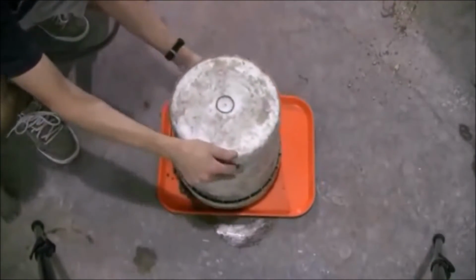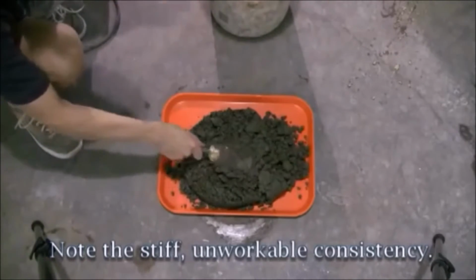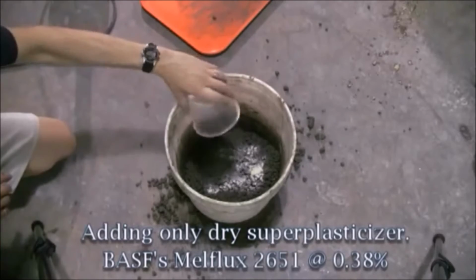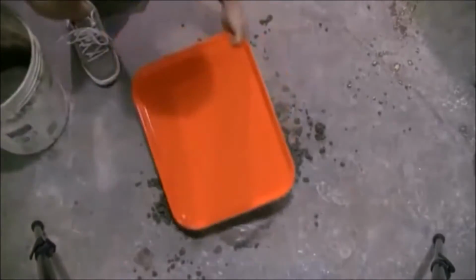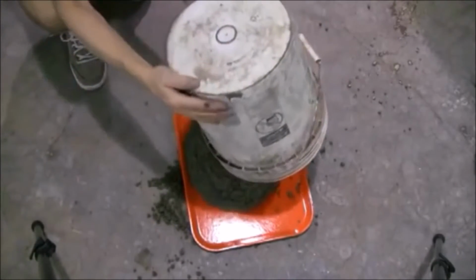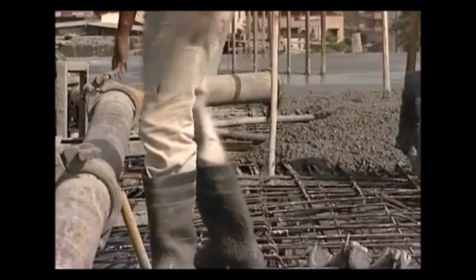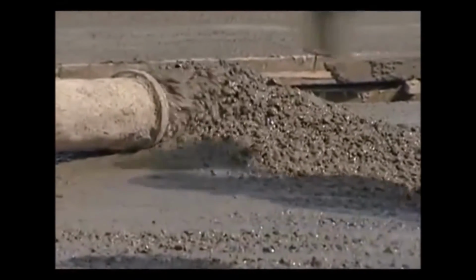As you can see, a batch of concrete with a water-cement ratio of 0.35 is inconsistent and hard to work with. With the addition of a dry superplasticizer, the concrete becomes increasingly more workable and fluid-like. Superplasticizers are classed as high-range water reducers and aren't necessarily sustainable by themselves, but in combination with SCMs and recycled materials can be used for non-structural sustainable purposes. Using this admixture, it clearly shows how we can increase the workability and pumpability, hence creating an easier to place and stronger batch of concrete.